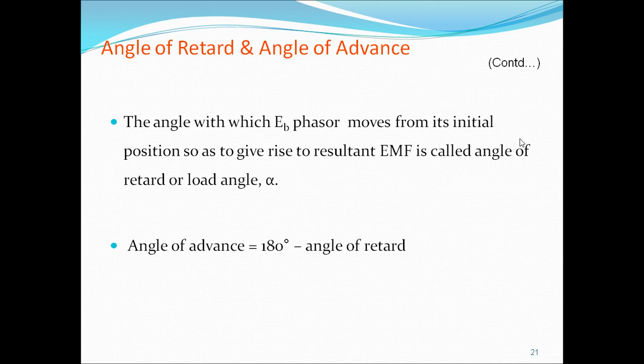So from this, what did we understand? We understood that when the load on the motor increases, the rotor falls back in phase and alpha increases. Falling back in phase means the axis between the rotor and the stator shifts, and then alpha increases. The load angle alpha of the rotor is adjusted to its new value and it produces the torque in the rotor which is sufficient to carry the new load and to supply the losses.